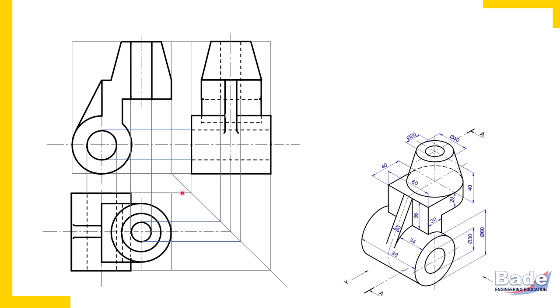So front view, top view, side view are complete. The only thing now is that in the newly generated surface, we should draw hatching lines. Now first, a very important thing: the newly generated surface due to cutting. This is the hole that is getting exposed. This rectangle is the original inner surface of the hole. So this whole portion is not to be hatched. This is a hole. There is no material here. So don't show hatching lines.